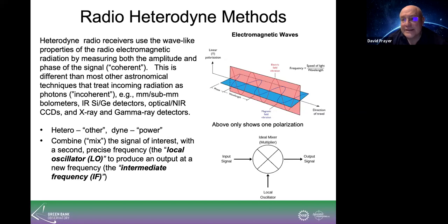And the reason we do this is you can see all the frequencies across the entire sky. Well, we go from 100 megahertz up to 116 gigahertz, but all that goes through and comes out the same back end of the telescope. Excuse me, I'll explain that. The same electronics. Otherwise, if you didn't mix it down to some common frequency, you'd have a lot of different systems. This way you just have one IF system, and then the LO mixer can introduce different frequencies such that you can mix everything down to the same common frequency.